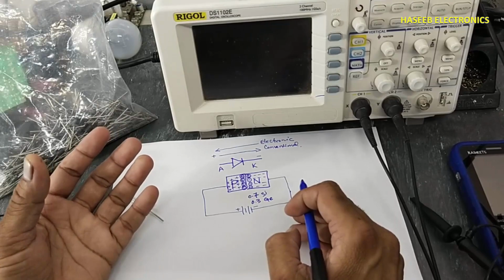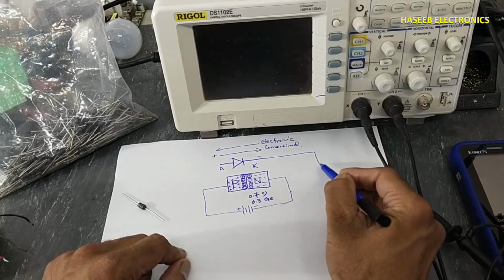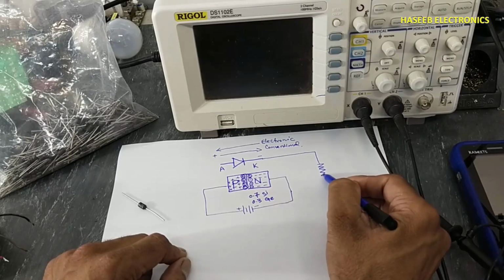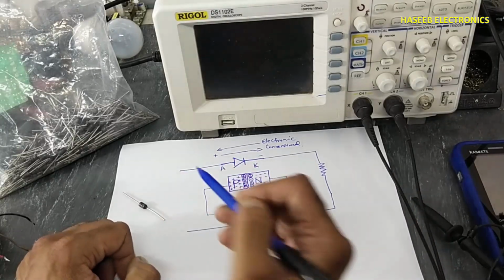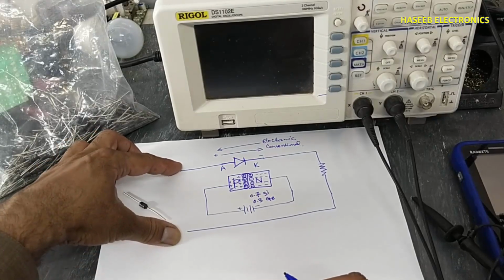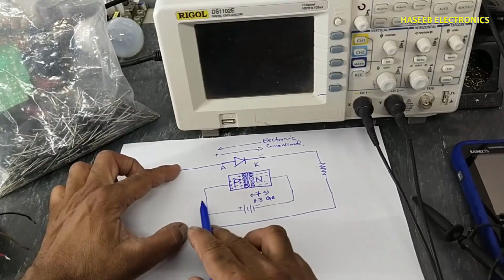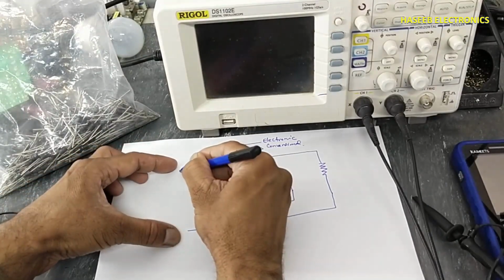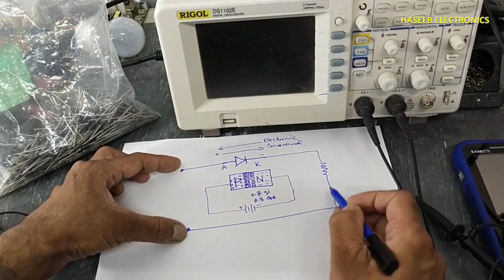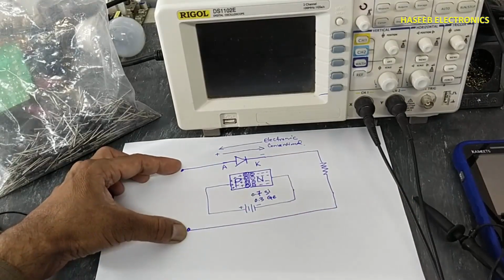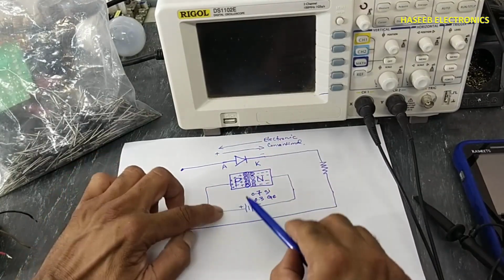To get a useful function from this diode, a load resistance, a load, is connected in series with this diode, and when it is connected to any voltage source which will provide potential, when the voltage at these two points exceeds 0.7 volt, current will flow, and it will flow in only one direction, as we discussed here.